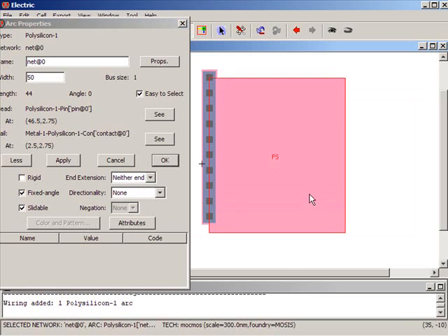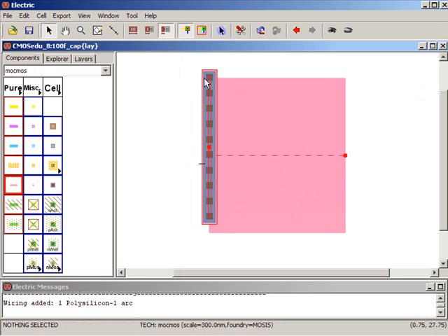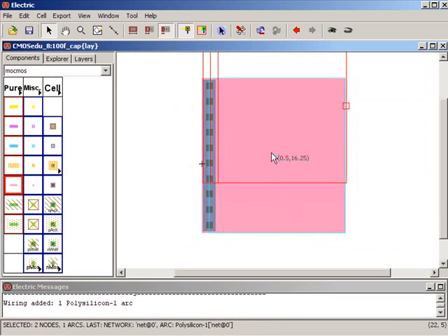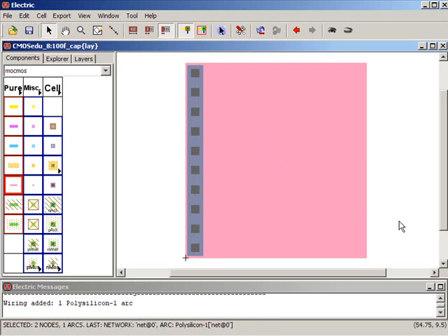And then if I move this up, it moves the whole contact node and the poly up. So instead of doing that, I'm going to select the contact poly here, and I'll move it down. And why don't we select the whole thing and move it now, and move it up and put the corner at the origin and hit fill. Now let's DRC by pressing F5, and there are no errors. So now we have our poly1 or bottom plate, and so there's a large capacitance from the bottom plate to